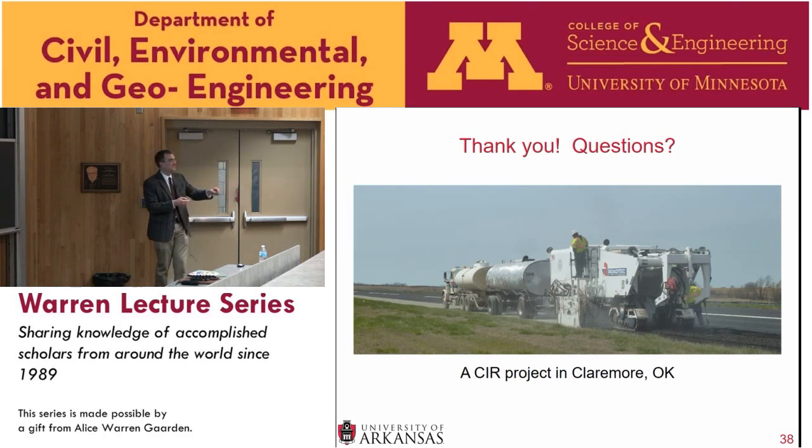I've already forgotten. Once you have provided this matrix, workability, compactibility, how do you ensure they are met in the field? So the question is, how do you make sure they're met in the field? I think that I see these more as being done before you go out in the field. So you take cores from the site that you're going to be doing CIR on, and then in the lab, you do your asphalt emulsion content, your water content, any sort of additive content. You do all of that to match the specifications, the metrics, and the compaction metrics in this direct shear test. And in theory, then that will ensure that you have good performance in the field. But we're just looking at the design portion before actually implementing it in the field.